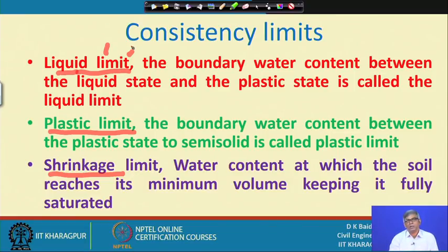And in soil mechanics, this water content determination is a very routine work. Most of the tests we do, we always need to find out the water content. For finding the water content, generally we take a sample in a particular can and take the weight, and then keep it in the oven for 24 hours at a particular temperature, and then the moisture will obviously be evaporated.